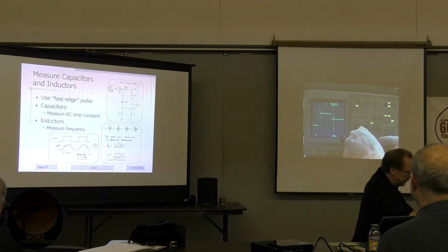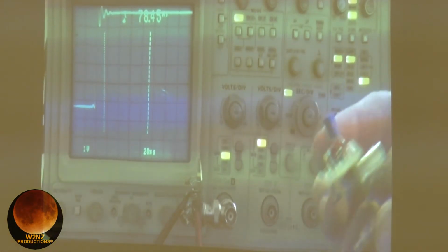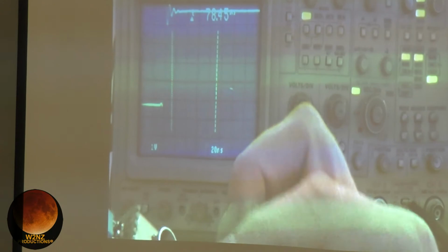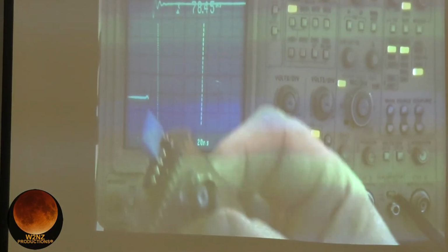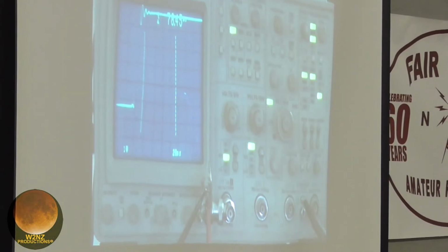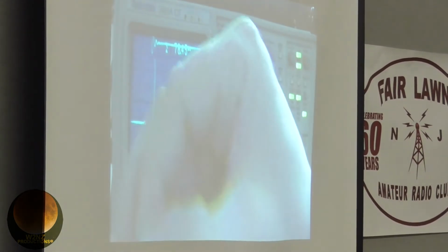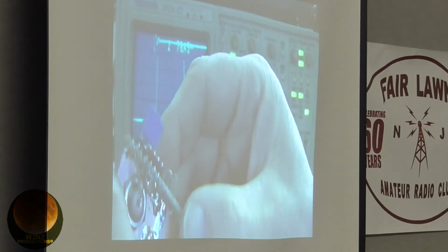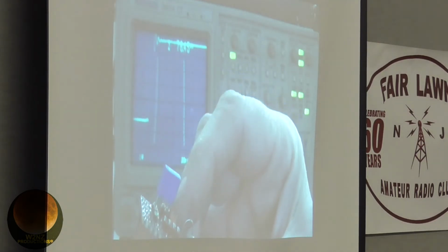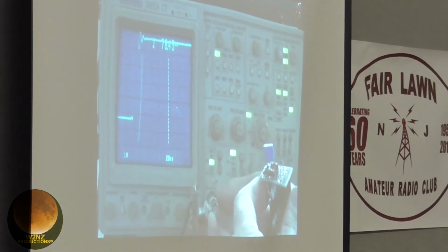All right, so we're going to use the same circuit. Here's my little test fixture. I like building a lot of test fixtures. Can you tell? Don't ignore the second half of this, I used it for something else. There's my BNC input, and I've got a couple little connections. Here's my unknown capacitor, and I'll stick that in here. Sorry, I have trouble doing this on camera. There we go. And there's my little 1K resistor. So there's my BNC input, 1K resistor, and the capacitor to ground.